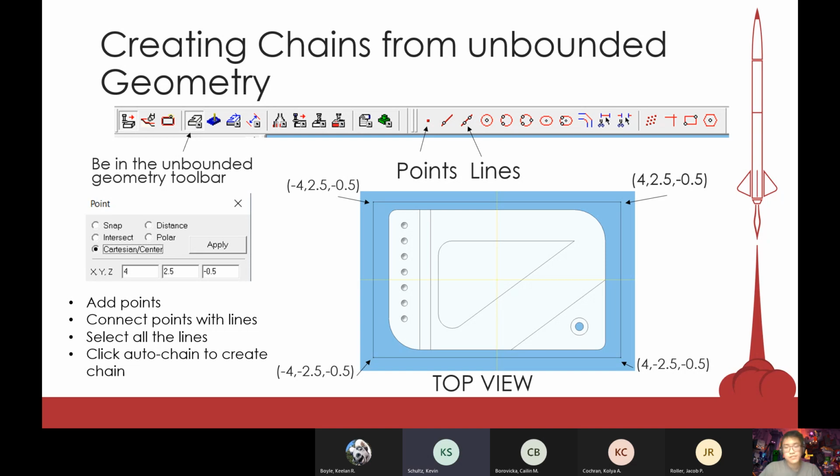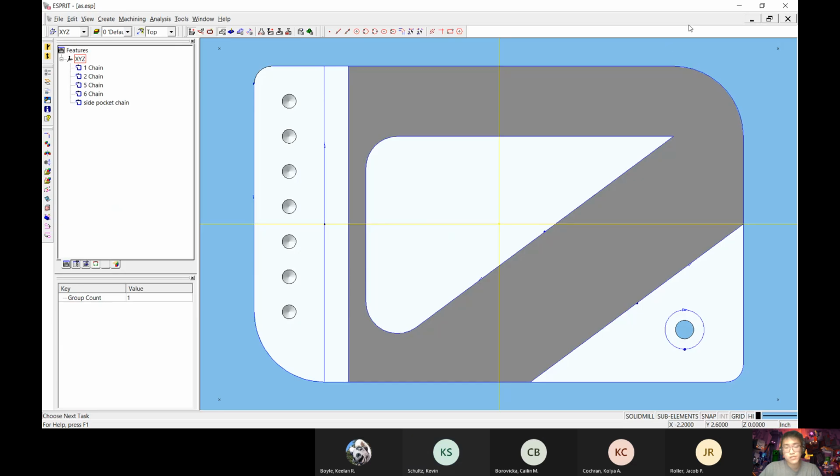Okay. So yeah, now we've created those 4 points, and now we're going to try to connect those 4 points with 4 different lines. So you'll press on line 2, which is the line that connects 2 points. Then you'll just click on each point, and make sure when you're clicking on the points, you see the symbol that says it's snapping to that point, which is typically an icon at the bottom right of the cursor, and snap all of those points together.